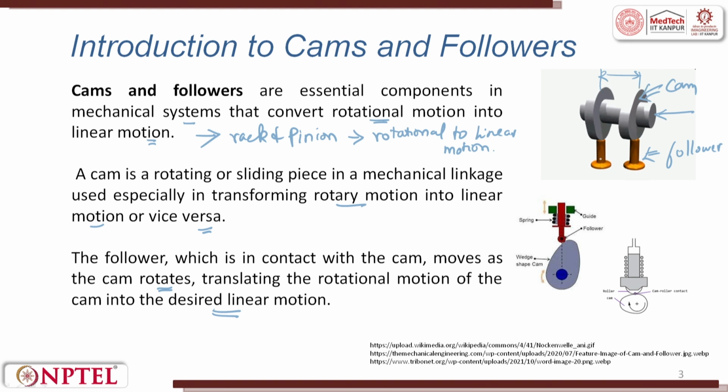If you look at the cross section, you can see here a cam. How does it look? It is not a circular disc, it is a disc which is offset by a distance. So, you can see here there is a center. So, you will have a cam which has a throw, a linear distance displaced.